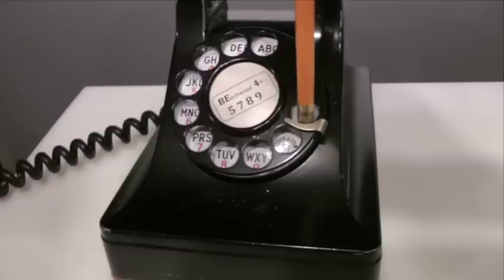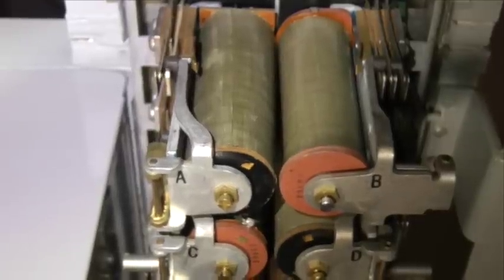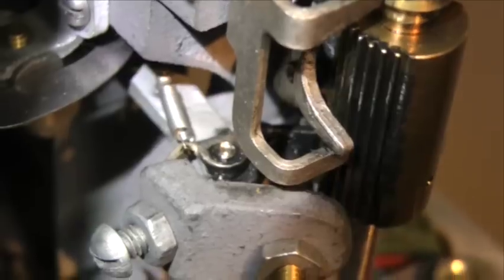Now let's watch the actions of the connector as it processes the reception of the units digit at normal speed. Remember that while the events are shown sequentially in the video, in actuality they occur simultaneously. I should mention that when the tip and ring wipers sweep across the bank terminals, they are electrically dead. This prevents any noise interference from occurring when these wipers contact any terminals being used by other callers.